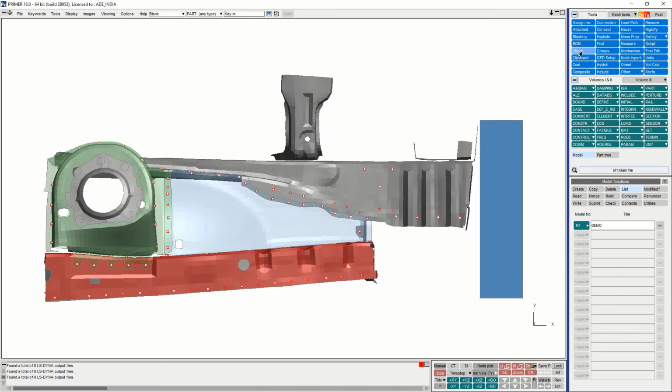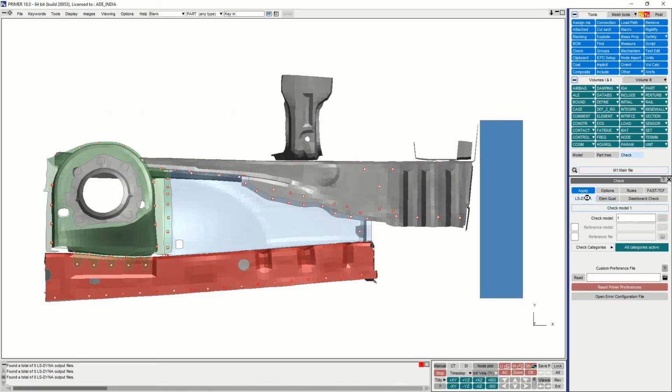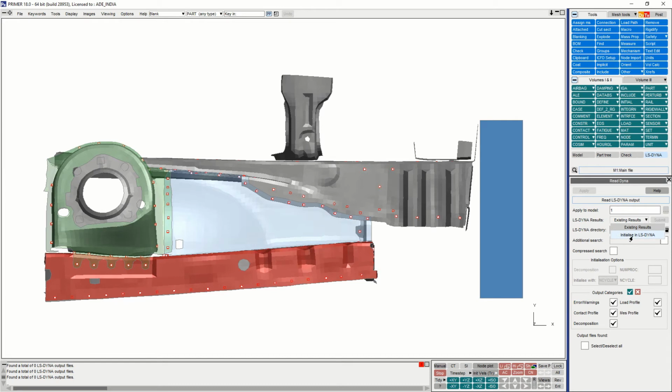So if we have a local installation of MPP LS-DYNA, we can use that in the checking tool. This is beneficial for checking load balancing and decomposition. So here we have our example model again. Let's initialize, but this time turn on the options for decomposition. We set the numproc value to however many CPUs we want to test.